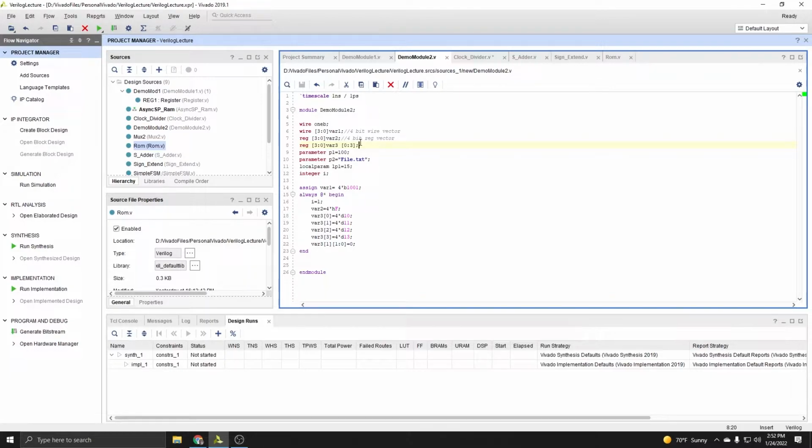Or if you synthesize the module and plan on putting it on a board, those values only change prior to doing simulation. Once you've run simulation, synthesis, and all that, those values are made constant so that they can be used to alter various elements of the module itself, to allow you to reuse your modules.